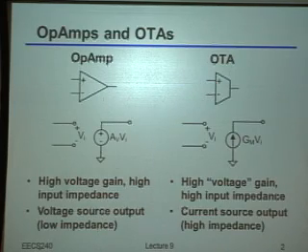Okay? So the first thing that I want to point out is perhaps some terminology that you've heard before, but I want to make sure that it's absolutely clear to everybody what the difference really is. You've probably heard many times about op amps. That's probably the first thing that you learned about, back in your original intro to EE class. But it turns out that in most of what we do in IC design, it's actually OTAs that'll be the most fundamental building block. To be clear, OTA stands for Operational Transconductance Amplifier.